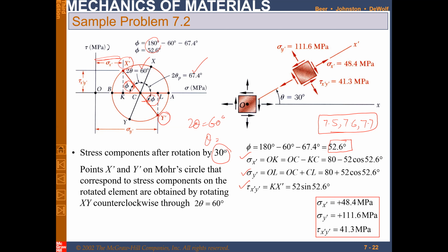We have to see that these applied conditions are going to generate some sigma max value, some sigma min value, and this will be at any particular angle rather than along the x-axis or y-axis. So as a good designer you have this information, what your maximum sigmas and maximum tau values are that will be generated at the end of the day at any particular angle, when these loading conditions come, right?